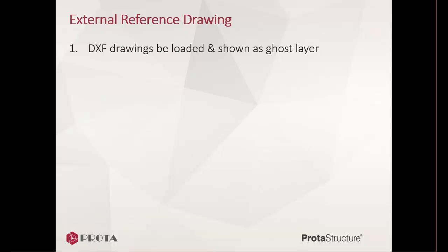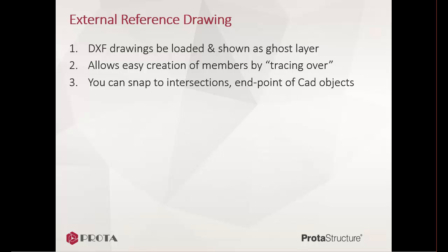ProtaStructure allows you to load external DXF drawings and show them as ghost layers in the plan view. This greatly eases modeling and creation of members, by simply tracing over the reference drawing. You can snap to intersections and endpoints of CAD objects. Further, each story can have a unique reference drawing.